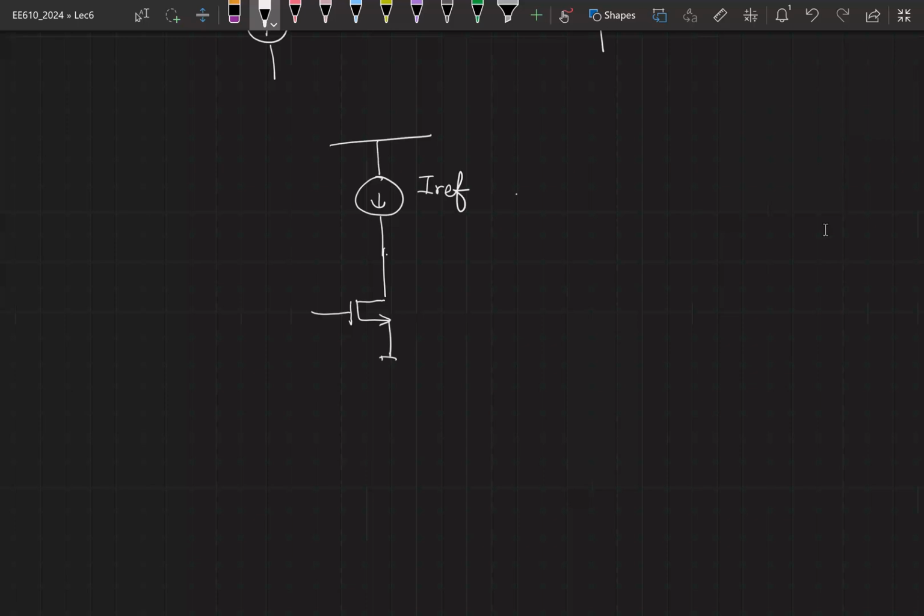And then we connect it to a MOSFET. And we have connected a battery which is tunable. Now, if IREF is flowing through this and some ID is flowing through this, if I take a branch out like this, I would expect IREF minus ID to flow into it. So now I have not connected this to any other node. I just told you that the difference current is flowing here. Where do you think it is going to flow out if I simply connect a wire like this?